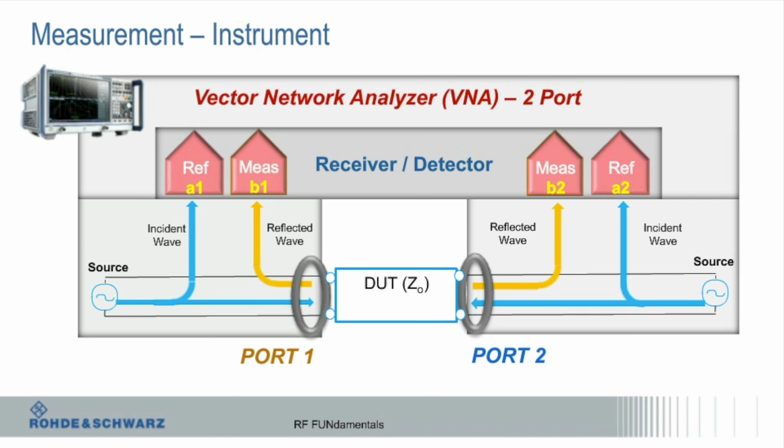Now they have electronic calibration modules. We call it an AutoCal, where it does all that for you. So it's pretty hard to screw it up. It's not impossible, but it's pretty hard. You connect those things, that's a connection here, and it does all that magically and calculates all the error coefficients.